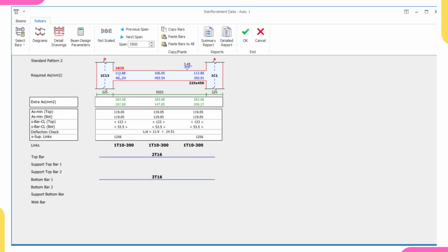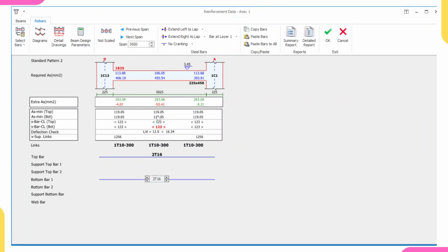So look at what this means. This is the area of steel required, and this means that we provided excess, 2830 excess area of steel, because this is the amount required. Then we provided excess. But if you decrease this to 2, it will start failing, because I've not yet provided enough area of steel. I still have to provide up to 4 to match this. So if I now increase it, that means I'm providing excess, which is okay.